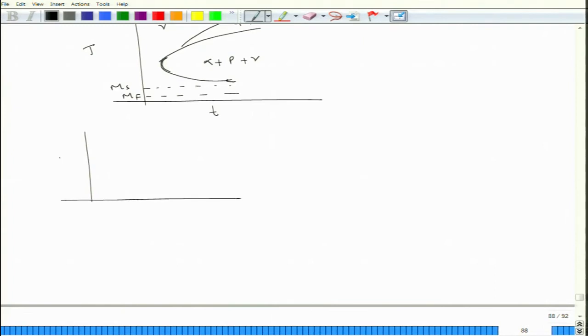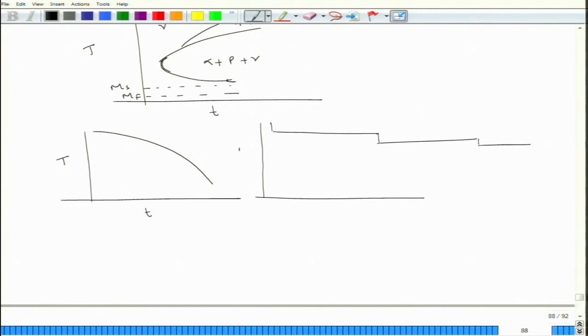Annealing: on the temperature-time diagram, the annealing operation would have a very slow cooling rate. This is one way. Another route could be that I take it to a lower temperature and hold it there for a long time, gradually holding it like this. That is how we get those transformations, and we call it annealing. Now, if we do normalizing, the cooling rate is a little faster. If I indicate normalizing in a different color, this will be my normalizing, with a faster cooling rate.